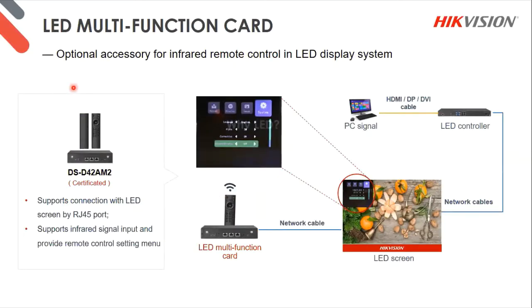All right, the LED multifunction card. What this basically does is add this little guy here that interfaces with the LED controllers and the monitors, like you can see, and gives you remote capability from the front of the screen to see what's happening while you're changing the display. Similar to your TV remote, you set up different screen brightnesses and contrasts and all those kinds of things from a remote from the front, to see what you're doing while you're doing it. So it helps a lot with that. Otherwise, you're going to have to go to the back and program this thing.